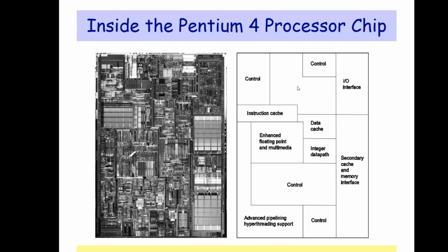Similarly, in the chip manufacturing process, if 100 ICs are getting manufactured and only 50 ICs are in good shape after all the testing is done, ready to send to the customer, working as per the requirement, let's say you have a CPU clock of 2.4 gigahertz and you are meeting that, and your voltage, current, all the PVT corner metrics you are meeting, and you have only 50 out of 100, then you have only 50% yield, which directly tells you that you have 50% loss in the manufacturing process.